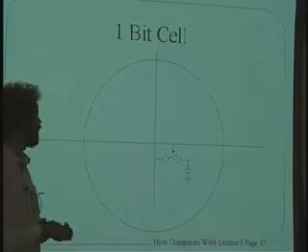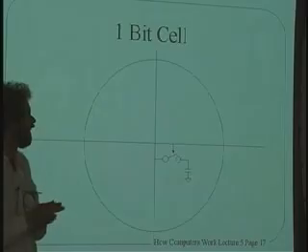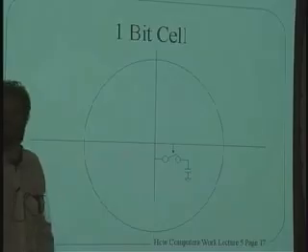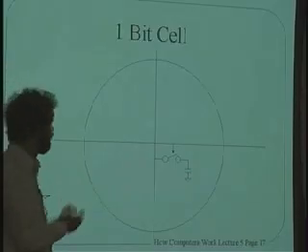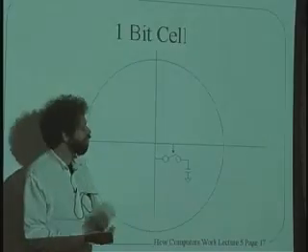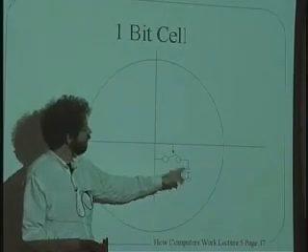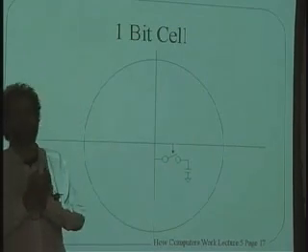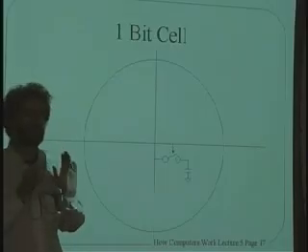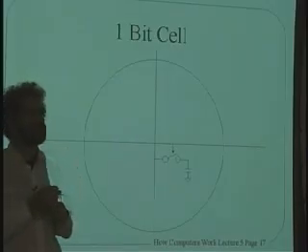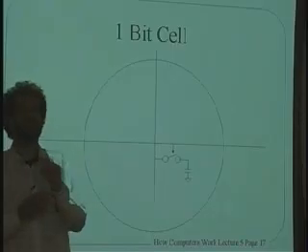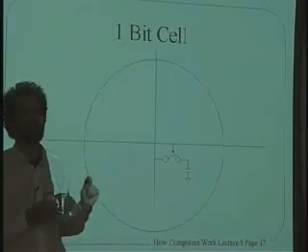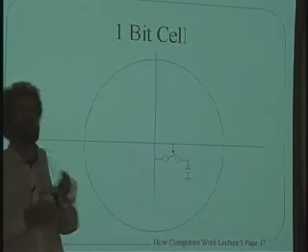If you live in a nice old house in this town, and you stop the drain with one of those little stoppers, what happens? An hour later, all the water's gone. Why? Because it slowly dripped by all the leaks that there were in the stopper. And in fact, the capacitors that these memories are made out of work exactly the same way. The insulation is not perfect, and it leaks. It doesn't leak so bad that you can't store anything there at all, but it leaks bad enough that after a thousandth of a second, a millisecond, you can still trust that the water's there, but much past that, you can't trust it.